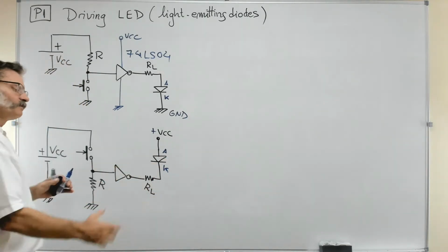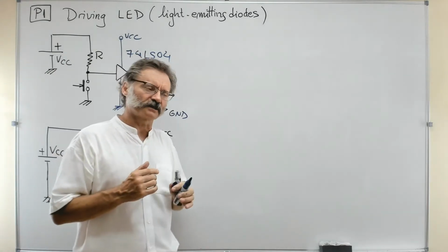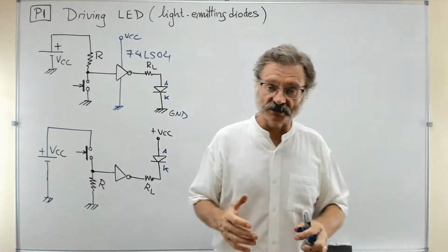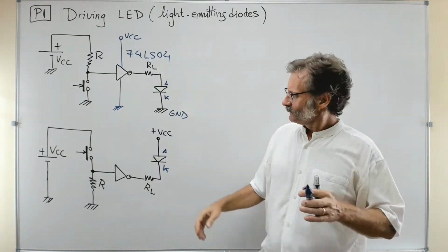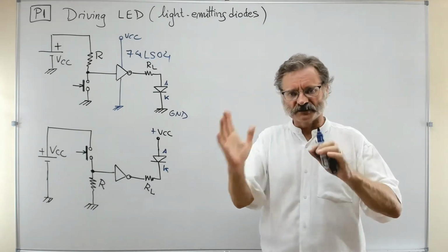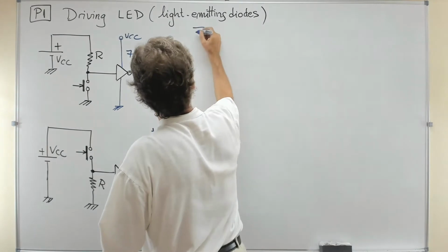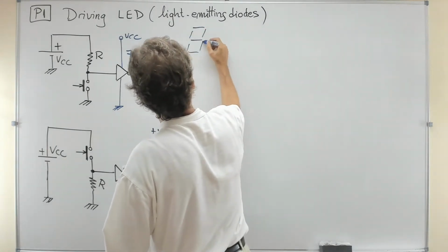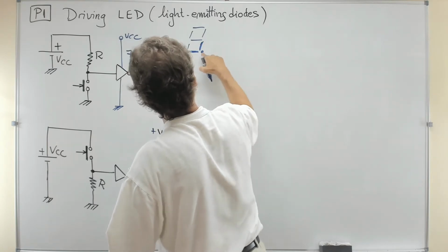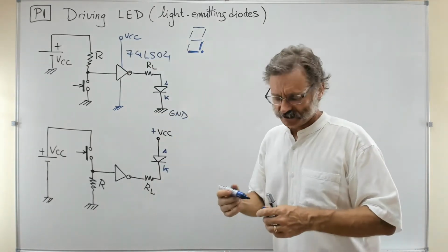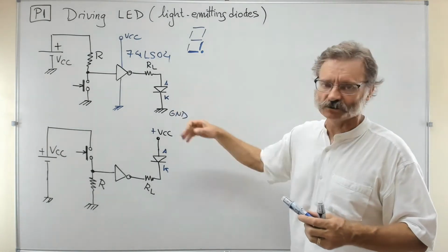This is not important now, but when you have several of them, for example in a 7-segment display to represent decimal numbers, you have 7 of them in the same device, generating the shape of a number. You have 7 segments, and every segment and the decimal point is nothing but an LED. They are all connected to a common cathode or a common anode.